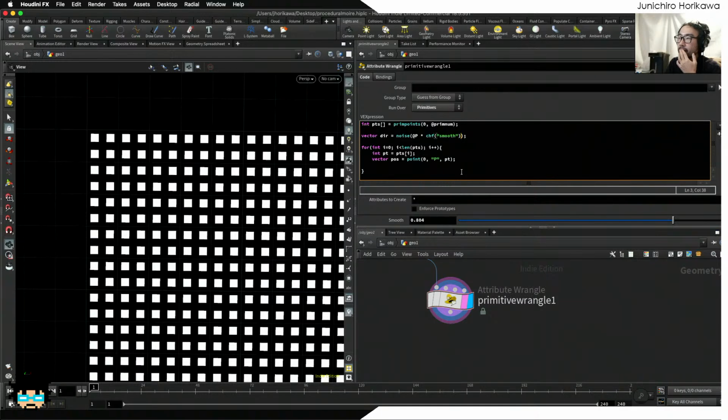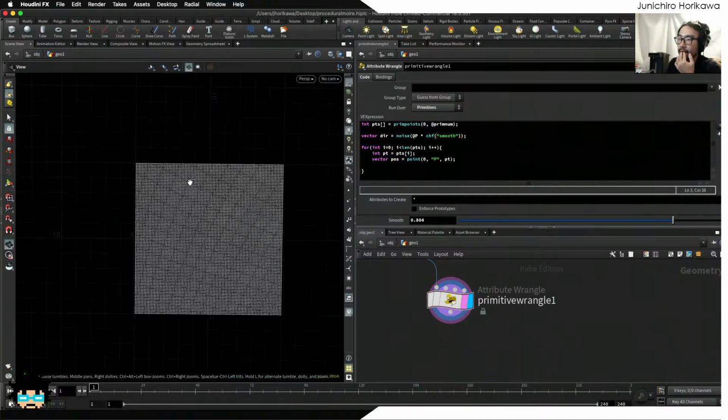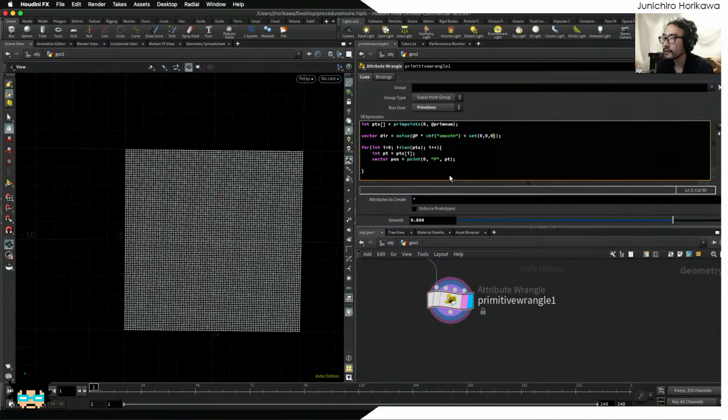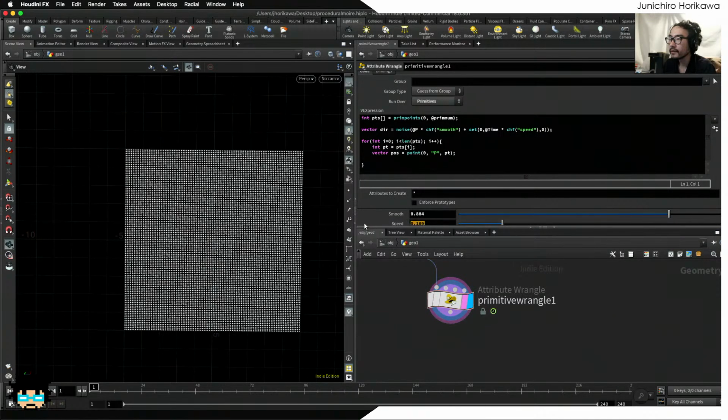let's see, I would like to animate this throughout using the time, so I am going to add 0, 0, 0, and I'm going to change this y value with a time value so that I can animate this noise value based on time. So I can say @Time. Alright, now I could also multiply this time to control the speed. Okay, now let's start with 1.